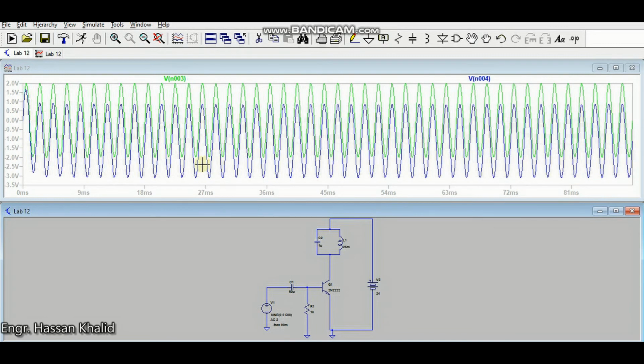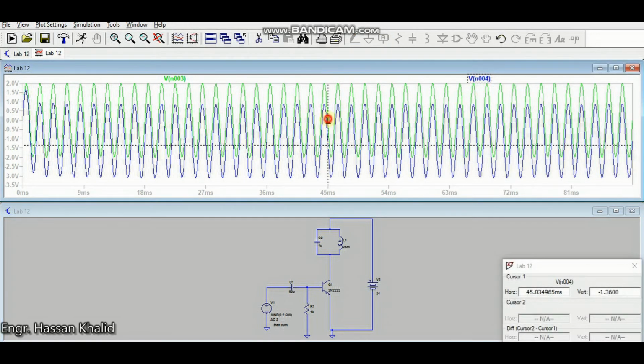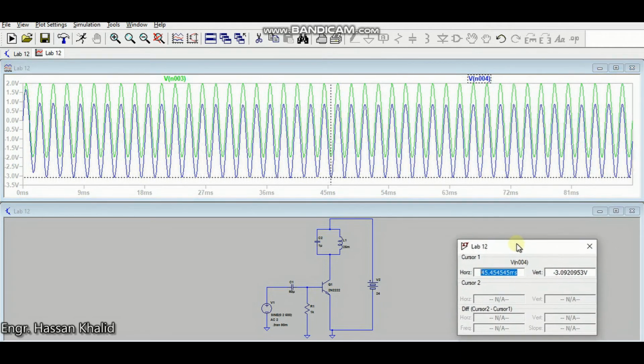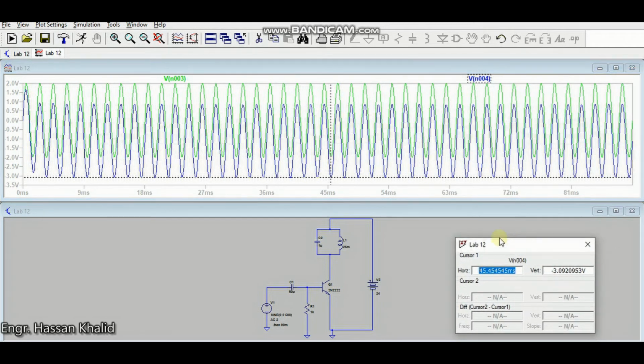With the help of the clamped voltage, you can easily see that the voltage being provided toward the base to emitter junction is now at max 3 volts at the negative side. It's negatively clamped, and this is equal to the 2 volt plus the 0.7 volt of that base to emitter junction diode.